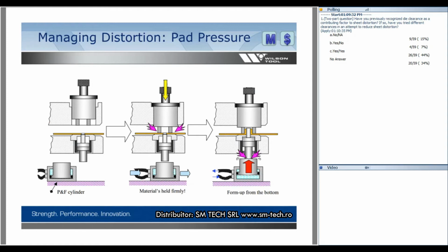But with that ability of holding the sheet flat, now I activate my lower ram, I can create all those extrusions. If I was doing a tubing assembly, lots and lots of extrusions, and it's virtually a flat sheet. Customers buy this, or sometimes it came free with the machine as an option, but they never started using it because it does take specialized tooling. But when you're fighting that sheet distortion, sometimes the up price for the tooling is the right solution.